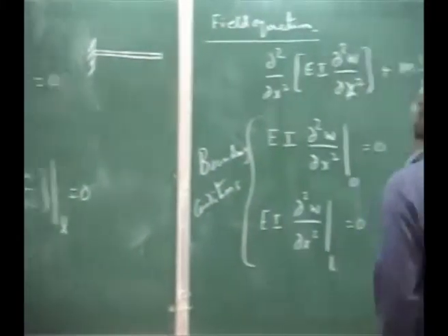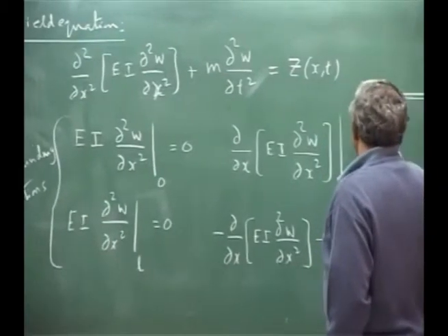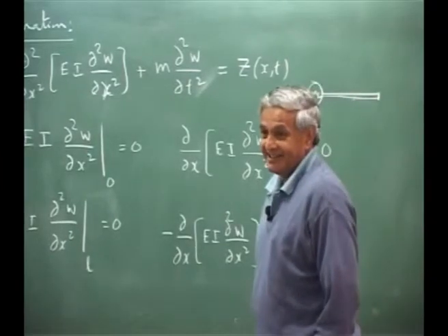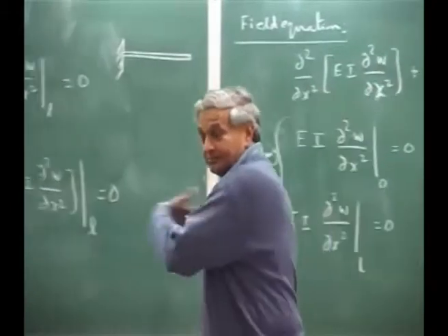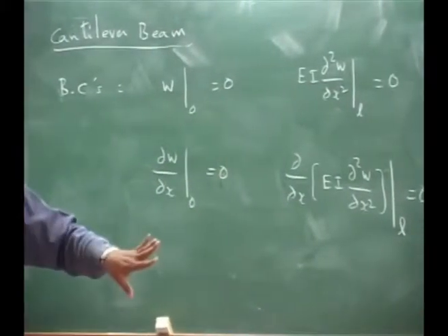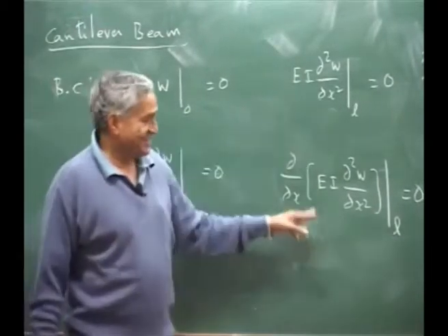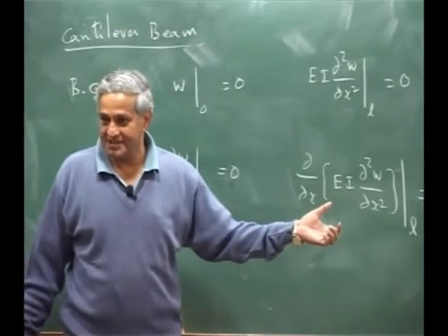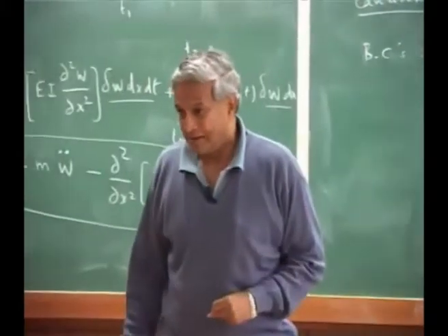These are the boundary conditions for a beam with the okay. This is one, this is another. Like that you can have a free beam. Free beam, once you leave it, you are not restricting. That means the same condition will come on the left side. You understand? Bending moment is 0, shear is 0.